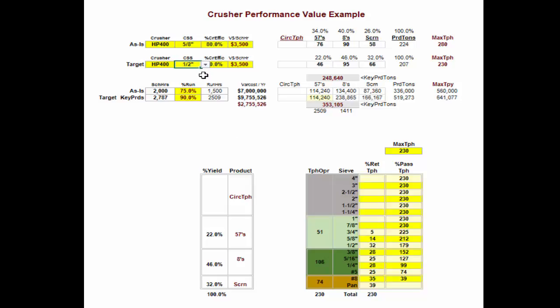There's a sweet spot. And for this example, it's the 5/8. That's the sweet spot. Once you know that, now you've got the gradation curve that you should be chasing. You can use that to estimate what you should be seeing on your belt scales, and you can turn that into percentages and create targets off those percentages. You can compare the throughput rate to the design throughput rate to begin with, but eventually you do the field testing to establish what the realistic throughput rate is with whatever efficiencies or inefficiencies you have in your process. And that's that example.